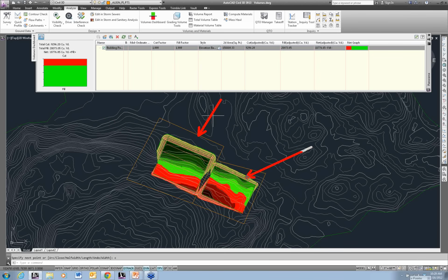So I'm going to create a bounded area. You select the surface that you want to add the bounded area to, and then use the add bounded button. Now what's it called? It's called add bounded volume. So I select add bounded volume. I select the polyline. And at first you might think, oh, nothing happened. But if you look up here now, you'll see a little plus next to the surface name. Go ahead and expand that out. And now I have that bounded area listed down below here.